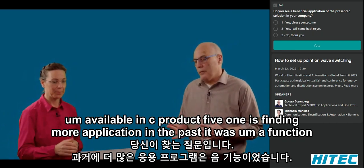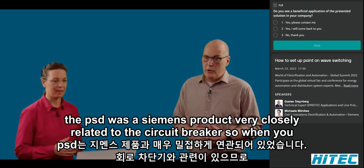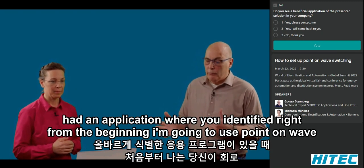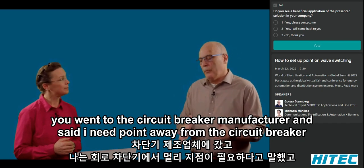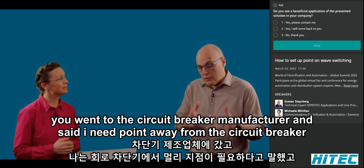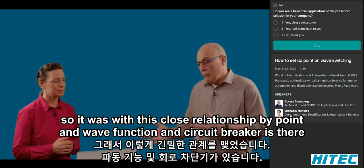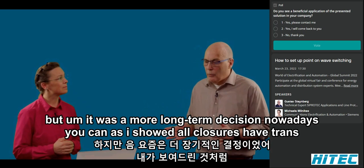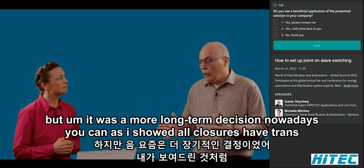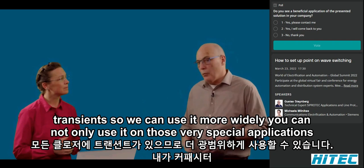In the past, the point-on-wave device was a Siemens product very closely related to a circuit breaker. So when you had an application where you identified right from the beginning that you were going to use point-on-wave, you went to the circuit breaker manufacturer and said, I need point-on-wave from the circuit breaker, and they put a special box next to the circuit breaker to do this. So it was a close relationship between the point-on-wave function and the circuit breaker, but it was a more long-term decision. Nowadays, as I showed, all closures have transients, so we can use it more widely.